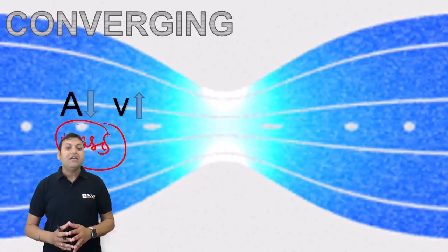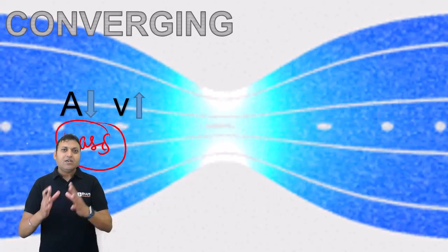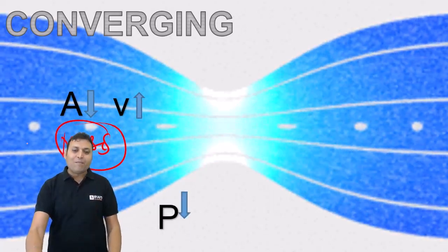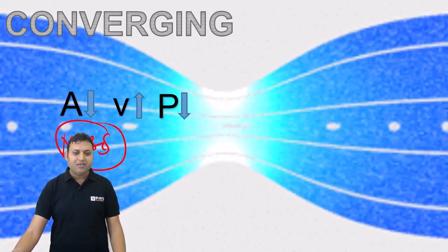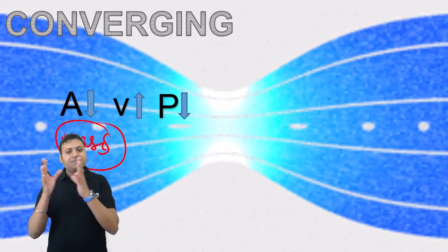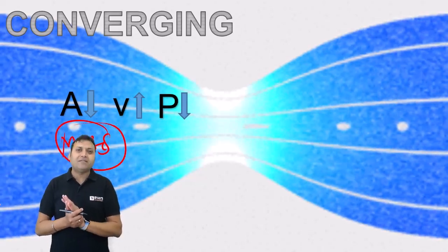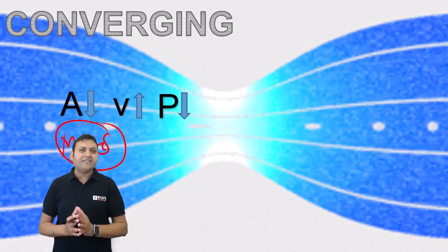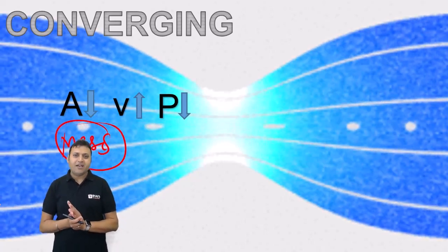Mass conservation. And when the kinetic energy of the flowing fluid increases, definitely the pressure energy of the fluid must reduce in the flow direction due to Bernoulli principle. This is called the Bernoulli principle. If the kinetic energy increases, the pressure will decrease. That is actually what happens in a nozzle. There is an increase in kinetic energy. That is why there is a decrease in the pressure energy of the fluid.